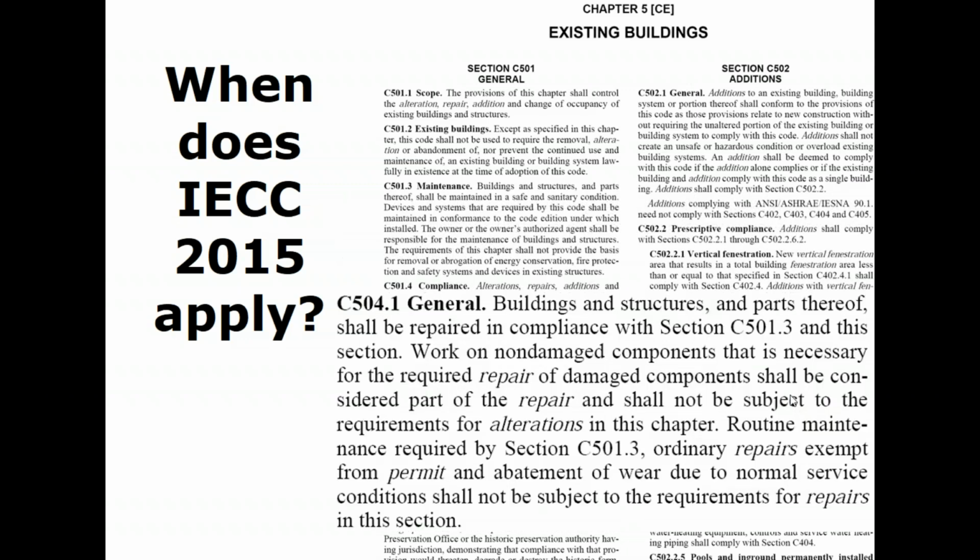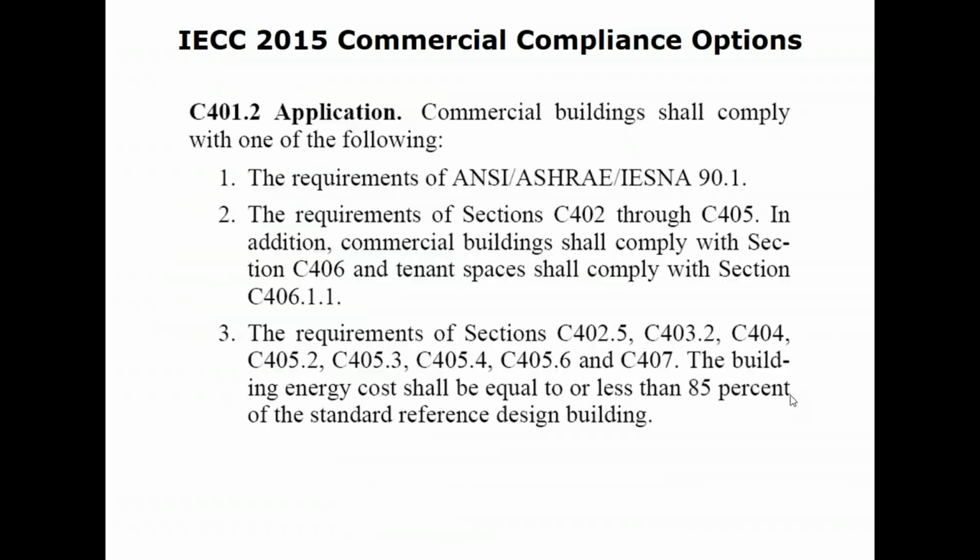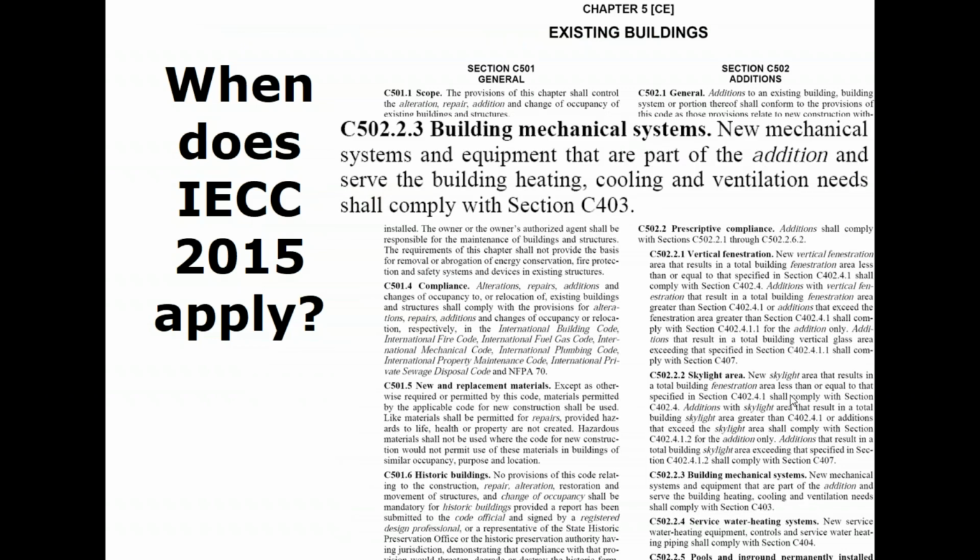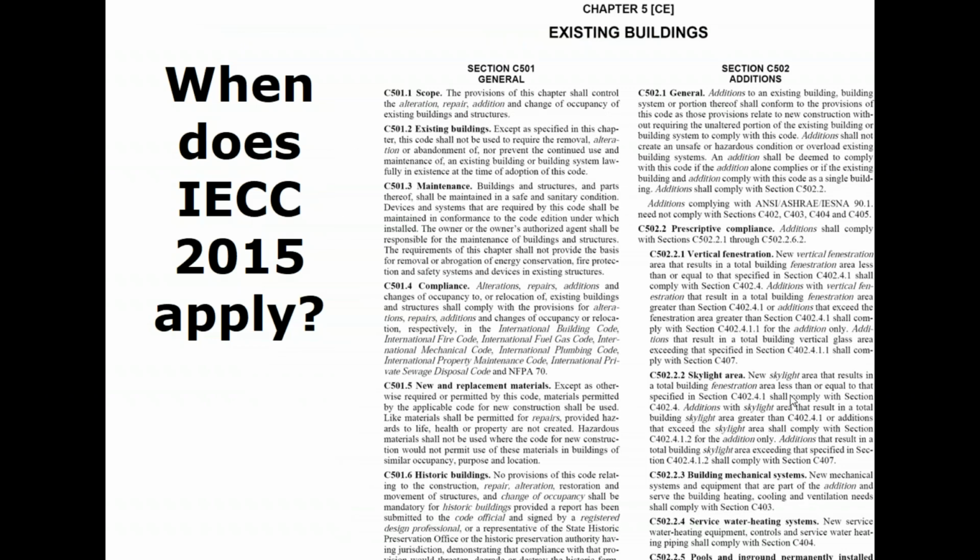Repairs as well. If you're going to repair something, the new repair needs to comply with the current code. You don't have to bring the whole system up to code, just the thing that you're repairing. Right? So the essential rule of thumb is, if you touch it, you need to make it comply with code. If you leave it alone, it can stay the old code for as long as you wish. I will mention as well that the real true exception is historic buildings. So if you look down the bottom right there, I didn't blow it up, I should have.